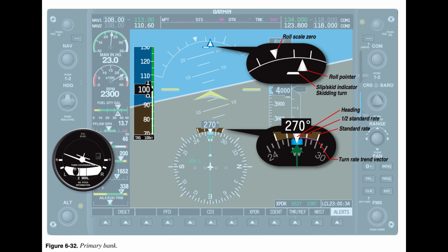Learning the primary and supporting instruments for each variable is the key to successfully mastering attitude instrument flying. At no point does the primary and supporting method devalue the importance of the attitude indicator or the power instruments. All instruments, control, performance, primary, and supporting, must be utilized collectively.